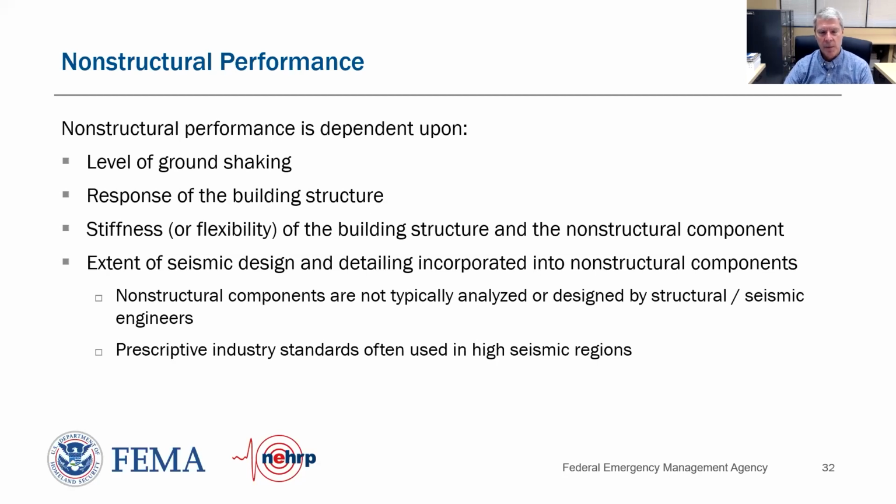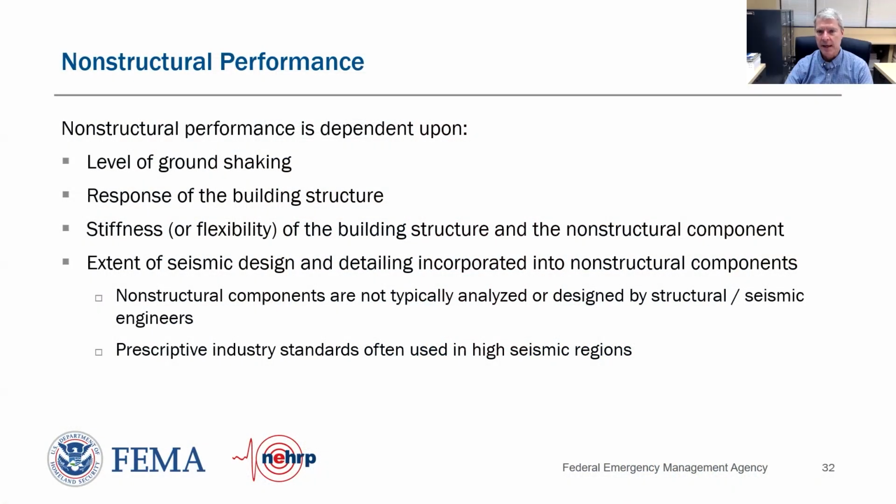When we look at non-structural components, it's a function of the ground shaking, which shakes our building structure. The more we shake the building, the more we're going to dislodge things, our non-structural components, which is our cladding, could be our ceiling systems, signage, canopies that are on the side of the building, etc. We're worried about those types of conditions if we're doing an RVS screen for a building, whether those could come down in an earthquake. And so we would like to identify those for corrective action.